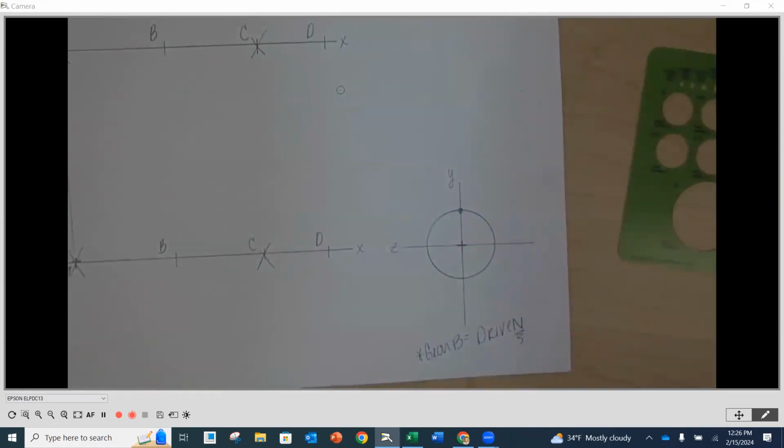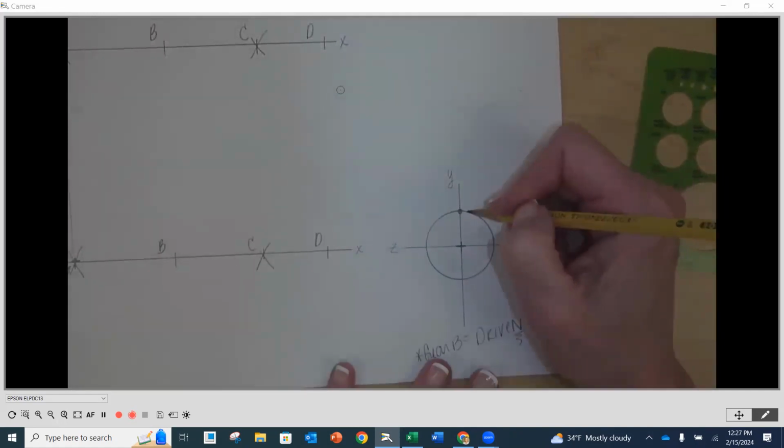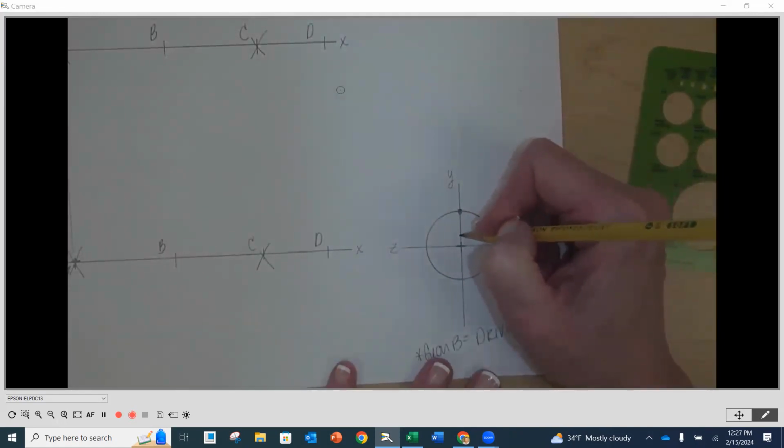And I have two forces that are going to be generated due to these two gears being in engagement. There's a radial force and there's a tangential force. The rule for the radial is the same. It doesn't matter if I'm driven or driver. The driven or the driver radial force is always going to go from the point of engagement and point towards the center of rotation.